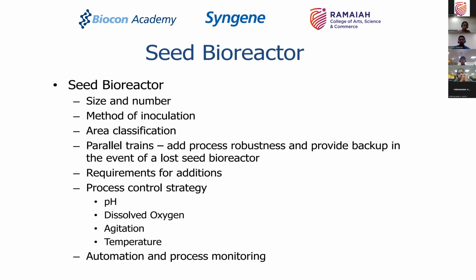Temperature is important because, just like living organisms, the organisms when they grow will produce heat, and this will raise the temperature of the media. You have to control the temperature of the media so that it does not grow excessive and kill the microorganism. At the same time, it does not grow to a stage where, if there are other contaminants present, and they will sometimes be present, they start to grow faster than the product of interest. So temperature control, pH control, dissolved oxygen control, agitation control, very, very important factors at every stage of the growth that we are talking about.